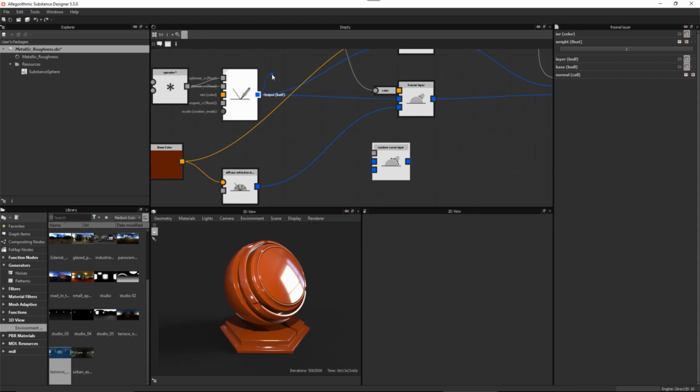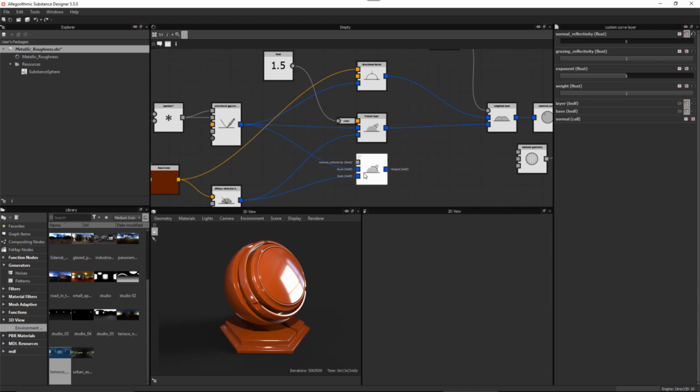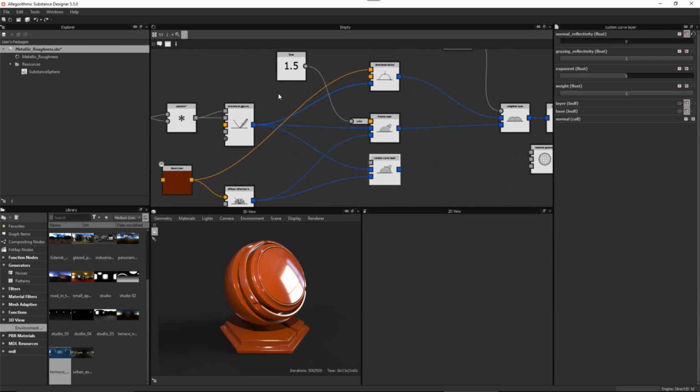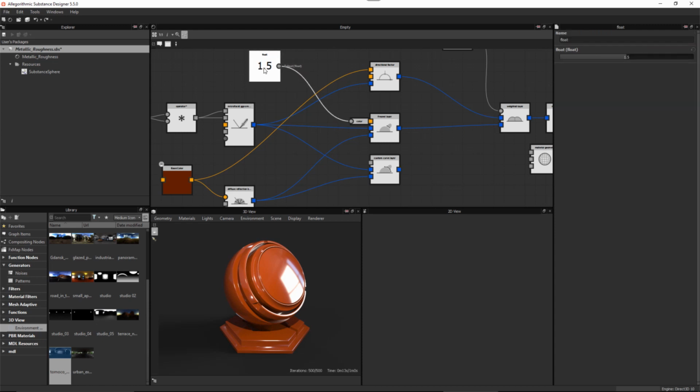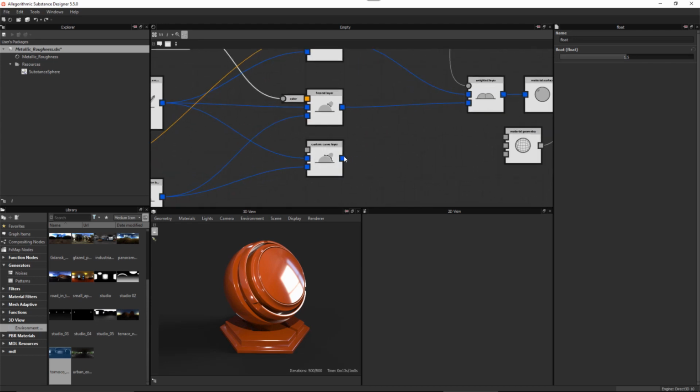So we're going to take our BSDF here, our GGX BSDF, and we're going to plug that into the layer. And then our diffuse reflection here is going to be our base. So here's what we have. Now we want to start to work here with our float value. So what I'm going to do, let's just grab this guy that we already have. And I'm just going to set this here. Here, let's do this. Let's take this custom layer. Let's take its output, and we're going to plug this into the base here of our weighted layer.